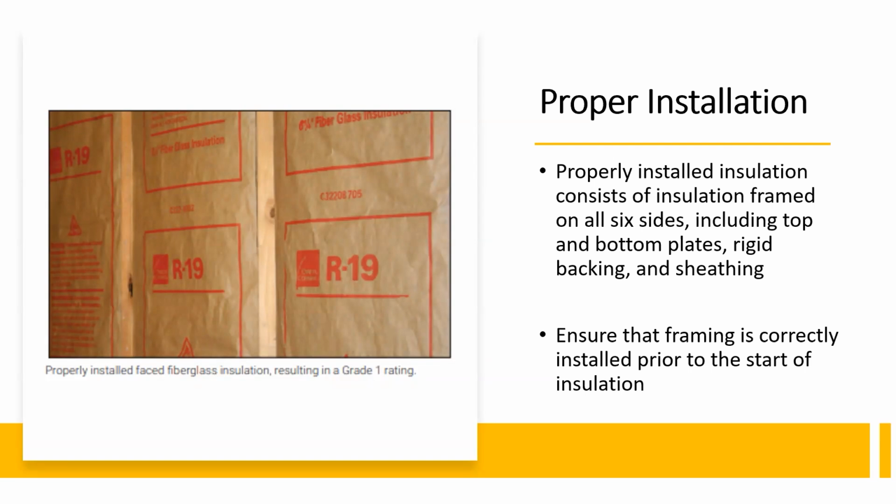If you're talking about a balcony that sticks out of, let's say, an apartment, and you have the actual exterior wall being insulated, you've got to have an air barrier on that too. It can't be exposed to a balcony overhang that's not insulated. So either way you cut it, it needs to be insulated on all 6 sides and have an air barrier on all 6 sides. So hopefully I answered that.